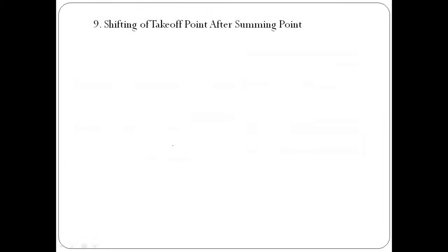Then let us try to understand what will happen if we shift a takeoff point after a summing point. Now it is a somewhat critical rule that we need to apply in very special cases. For example, if we have a takeoff point and we want to shift that takeoff point after a summing point, then what do we need to apply?